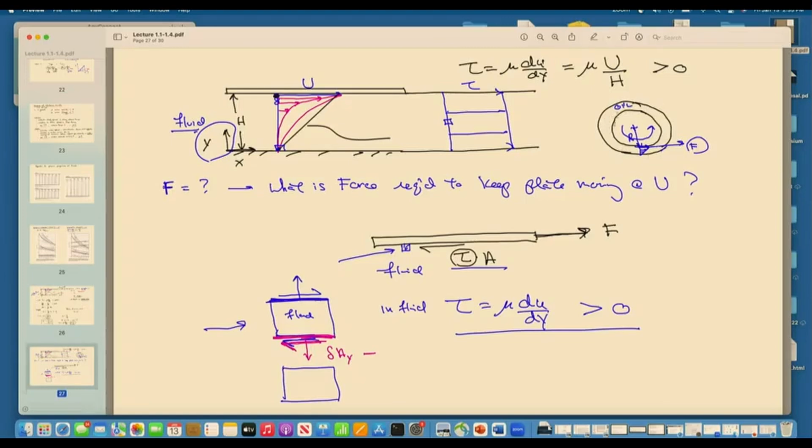You might have some torque or force imposed on the inner cylinder, while the outer cylinder is at rest. If you unwrap it, the problem can be explained using this configuration, where you have the oil in the gap and the wall of the inner cylinder moving at some velocity, r omega, the radius times the angular velocity, which gives you the linear velocity.